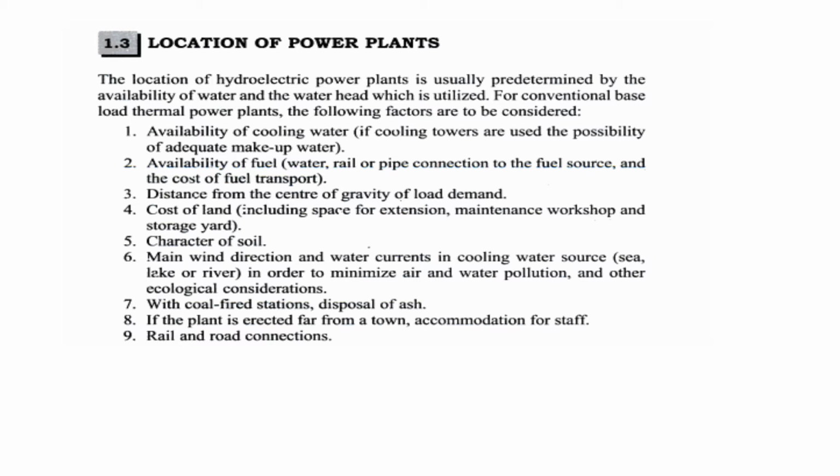Whereas a thermal power plant and a nuclear power plant, we have to install where we have a huge amount of water circulation, mostly near the sea. We have abundant, unlimited quantity of water, so that can be used for cooling. So we have desalination plants, and we have to purify the water. We have to treat the water, feed water treatment. Then it will be used in any power plant, whether it is thermal or nuclear. So that is the foremost important point to be considered before selection of a power plant. Near the sea, mostly, we will be choosing the site.